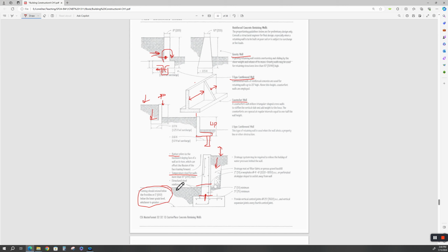And that is not structural steel reinforcement. That is concrete reinforcement. But that's fine. It's still part of the concrete, reinforced concrete. They don't refer to it as structural steel. It's rebar, okay? It's for reinforced concrete. And you'll see this J-hook, JL coming up. They'll pour this foundation, and then they'll probably tie the vertical rebar to it, unless it's short, then they'll run it all the way up.